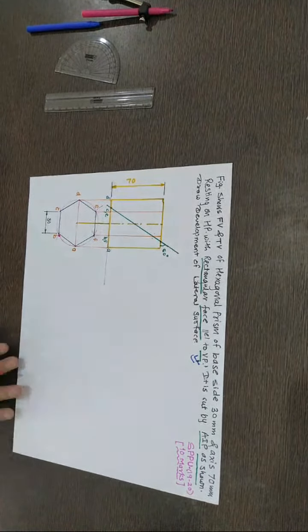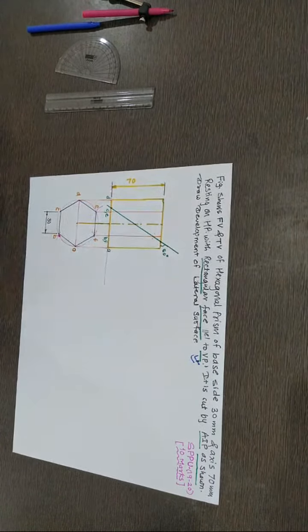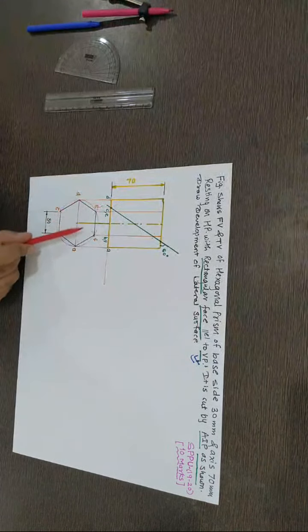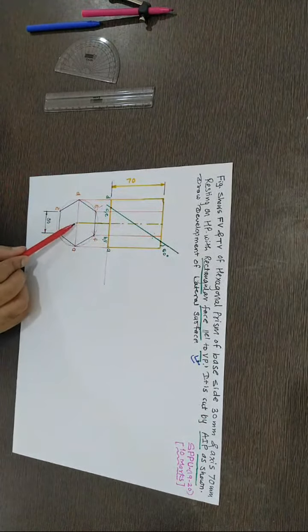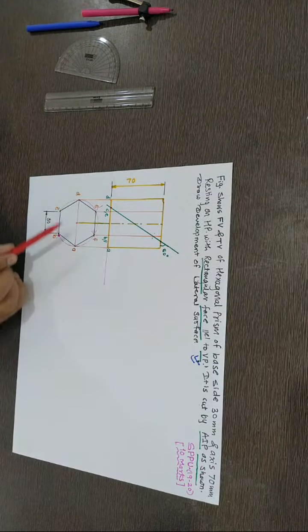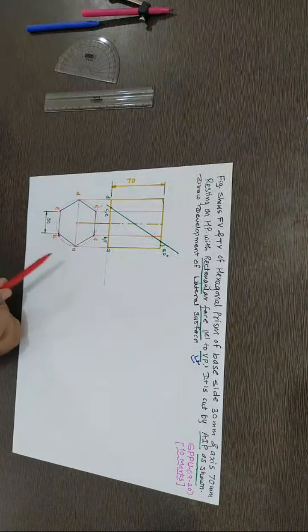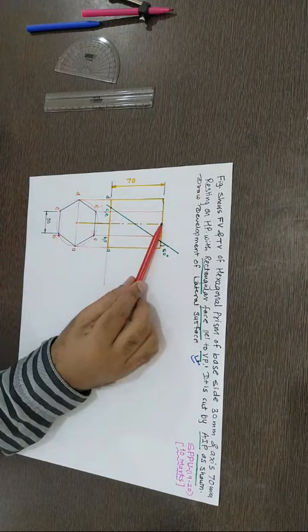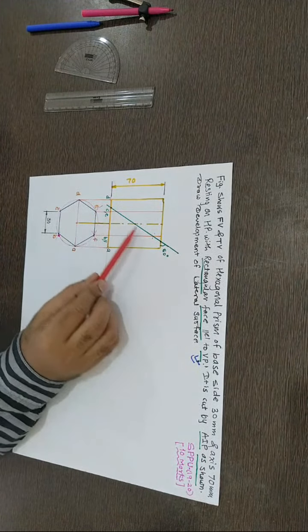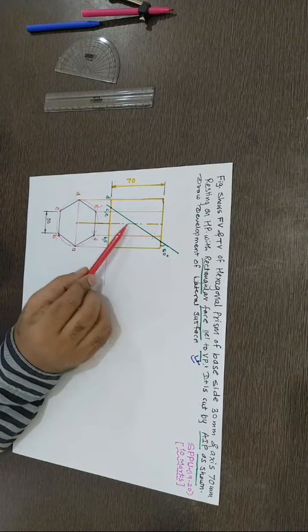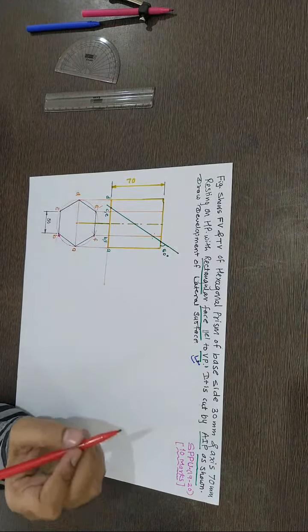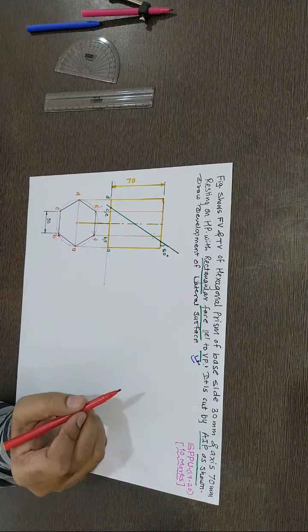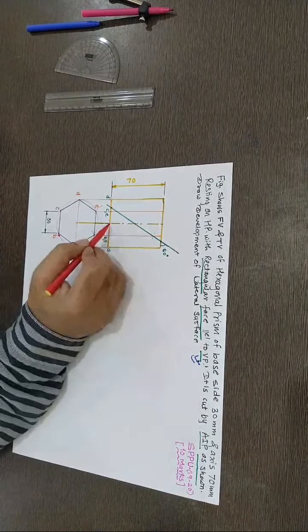So let's start. I have just drawn this hexagon with the circle method, drawing first a circle with a radius equal to the side 30, axis side 70. Take a radius, mark from this 2 points A and D, arcs of the same radius, join those points, axis side 70, join it. This angle is 60 degrees for HP, but it is taken at this point because it is bisecting the axis. So this is at 35 mm from both. So let's start.